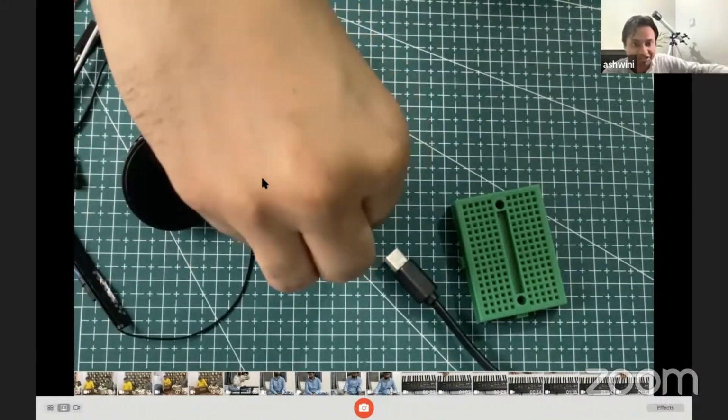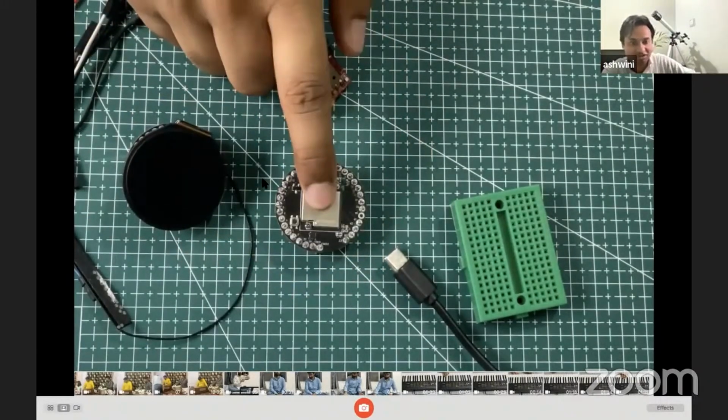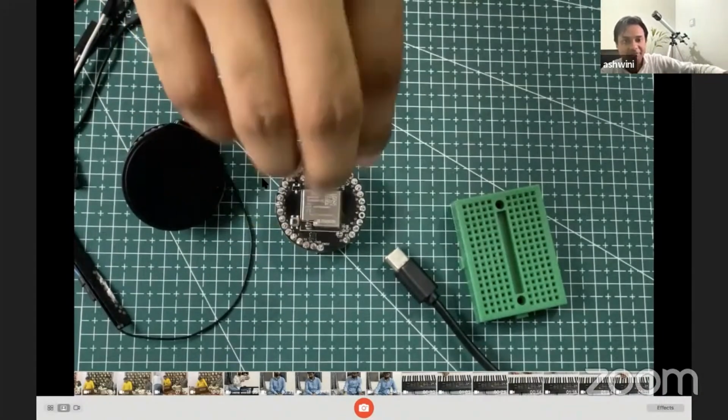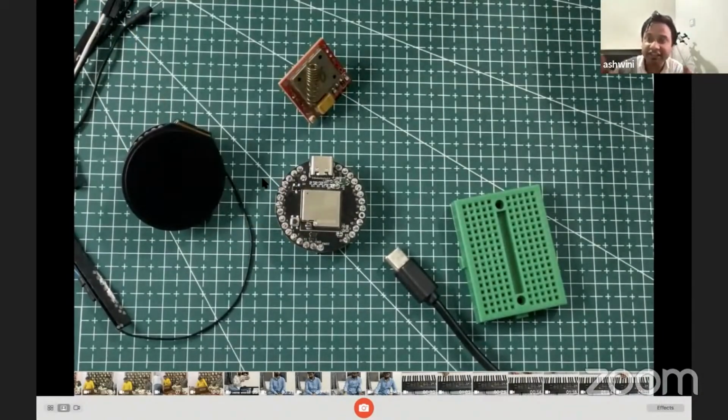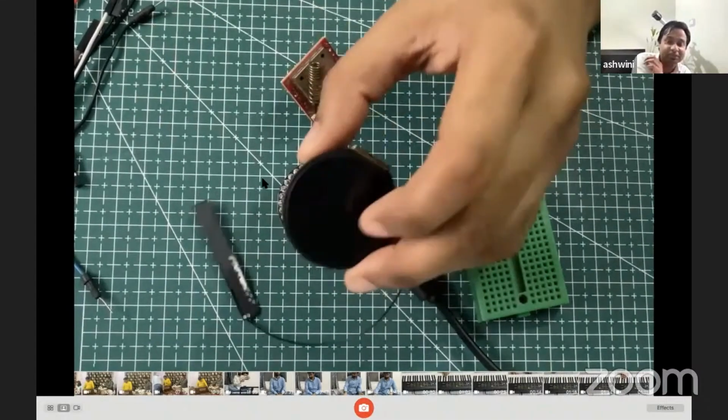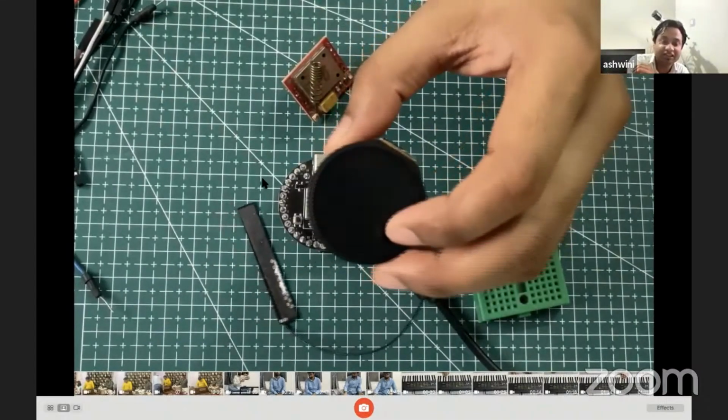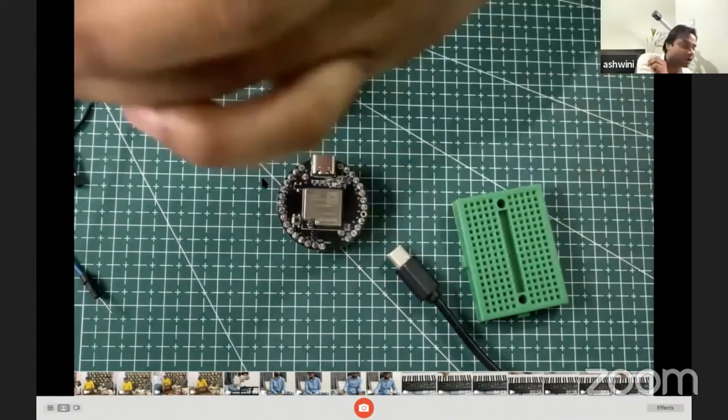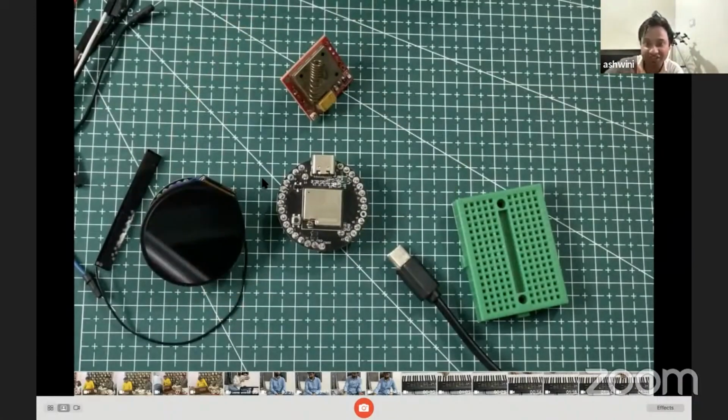This acts as our main chip, where we do all the programming and all the stuff, and we will program it using that. And then the second thing you need in the phone is the keypad or a display to show the incoming call and other things. In older times we used the keypad, but now we are going to use the touch display. So here we are going to use the round touch display. This display model is GC9A01 round display. But you can also use other kinds of touch displays, but those displays are a little bit bigger, so your phone will become a little bit bigger.